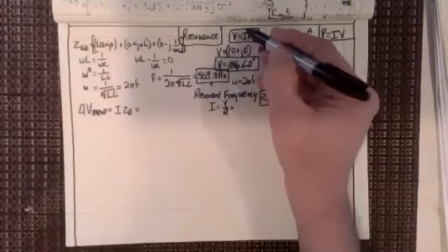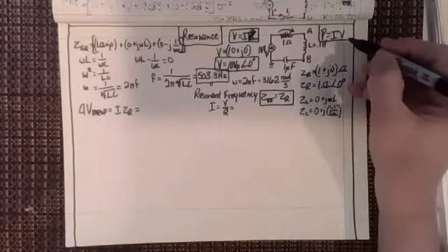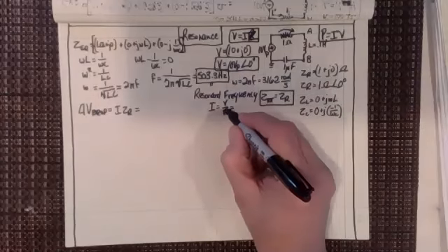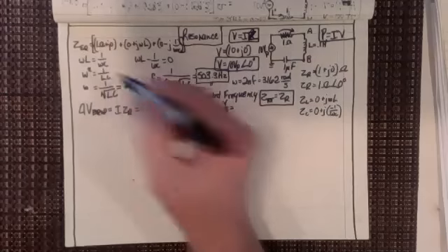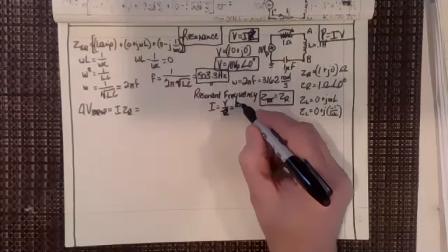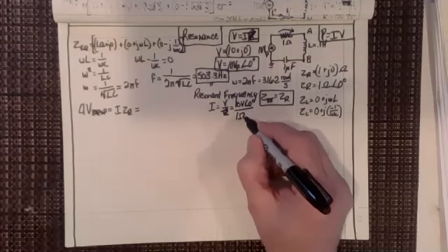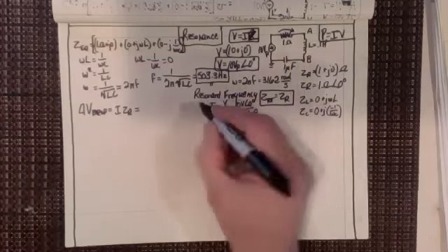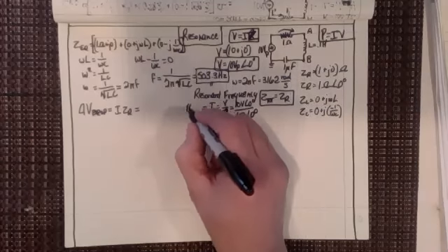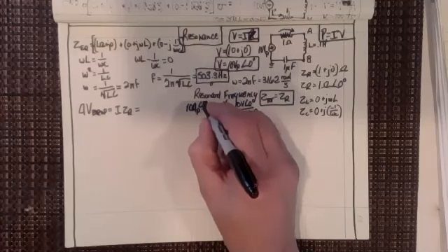Or in this case, I really should be using Z here, and that would be V over Z, but you get the general idea. Because it's only resistance, I can say that it's 10 volts at an angle of 0 degrees divided by 1 ohm at an angle of 0 degrees. So the current equals 10 amps. Those, of course, are peak amps at an angle of 0 degrees.